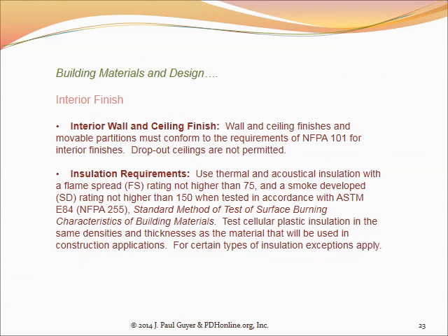Smoke, as I indicated, is a big hazard in fires. More so, it's now recognized, than flames as far as life safety is concerned. And so the finish materials in buildings, the wall coverings, the carpets, the ceiling system, are now manufactured from much more fire-resistive material than they used to be, and they have a lower smoke development rating.